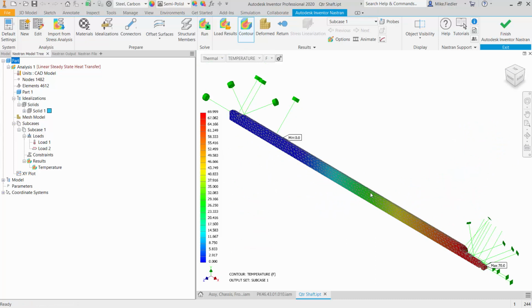Now the next portion of this is, remember we were cooling this down so that hopefully we can insert it into the hole there so that ultimately we can get some sort of interference fit. So our goal was to figure out by how much this shrinks, right? And then what are the stresses as a result of us doing this thermal loading on it.